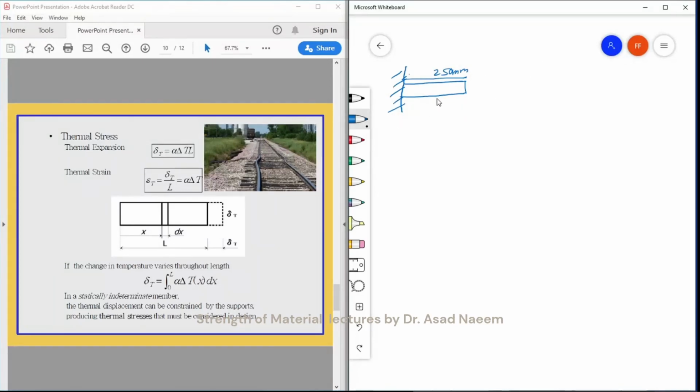and we have to calculate, there is a temperature change, and this can be any material, bronze or aluminium or steel, and its E is equal to 100 GPa. Its alpha, which is the thermal expansion coefficient, is equal to 16.9 into 10 raised to power minus 6 per degree, and then we can calculate, and the temperature change is, suppose, 40 degrees.